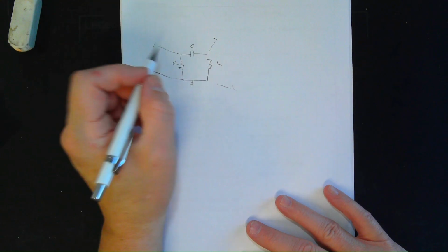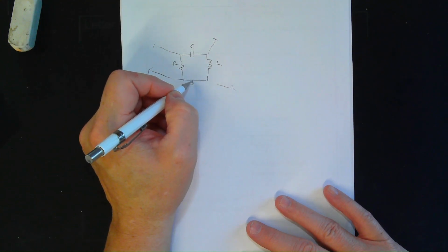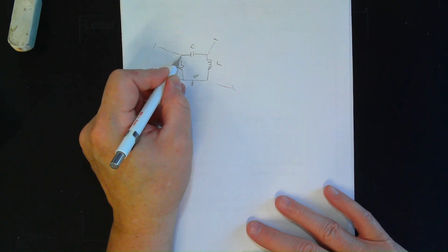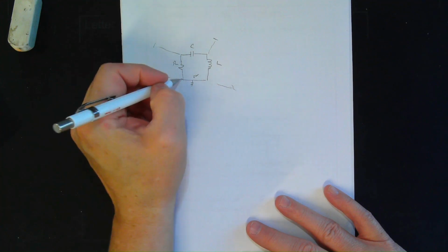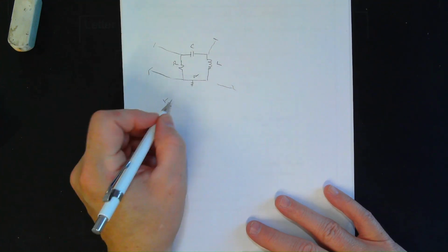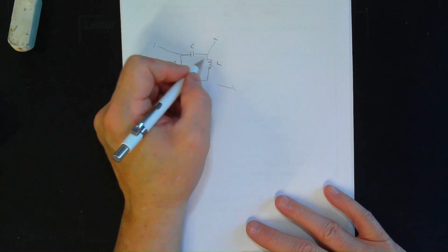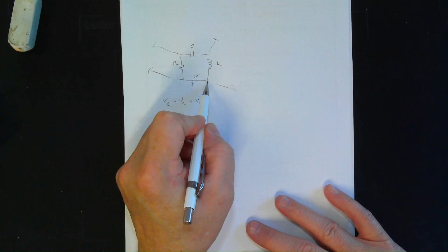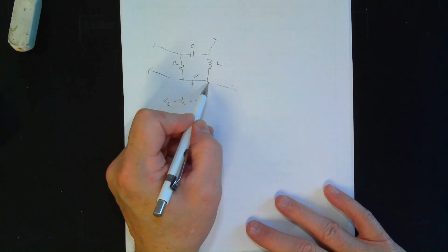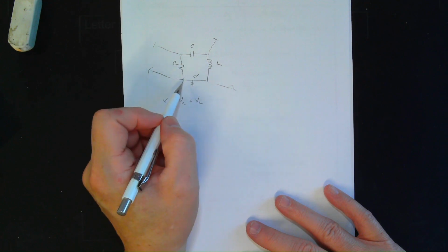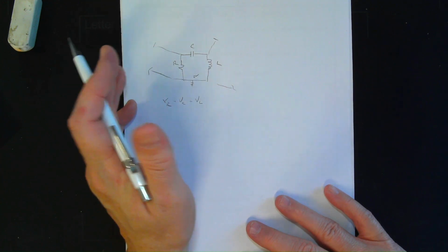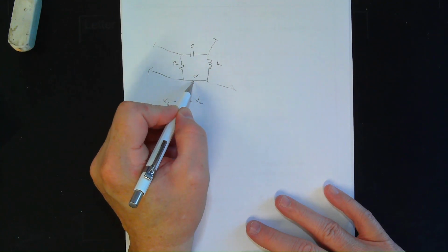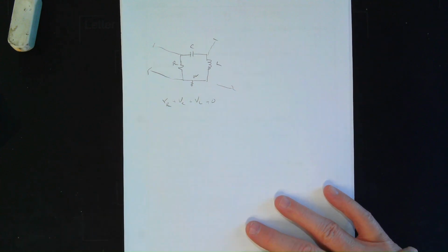All right. So as I go across here, so ground, that's 0 volts. So if I were to say the voltage across here, call that VR, going around, and then the voltage going this way across here, C, VC, plus the voltage across here, VL. Well, I know when I get back over here, the voltage is 0. I started at 0, I'm ending at 0. Somewhere in here, there's voltages going down or voltages going up, what have you. But in any loop, if you sum the voltages of all the elements, it has to be 0.